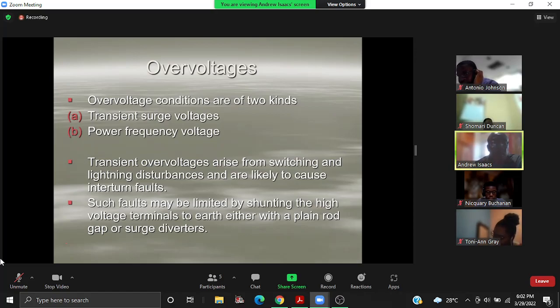Anyway, at the top of your transformers, you would find the lightning arresters. And these are there not just for basic protection, but to prevent these overvoltages that we are talking about. Because although it is not visible, it does create significant vibrations for your transformer and can therefore disrupt core bolts and that sort of thing, which then lead to all sorts of winding faults.